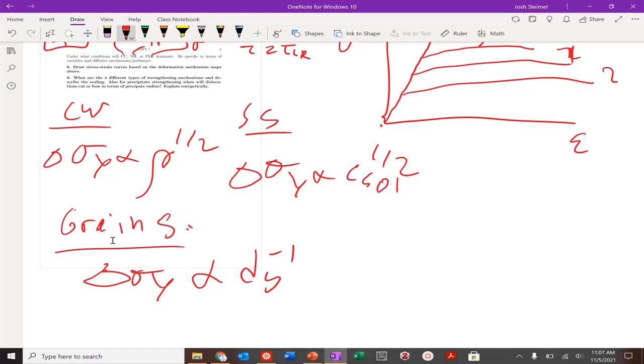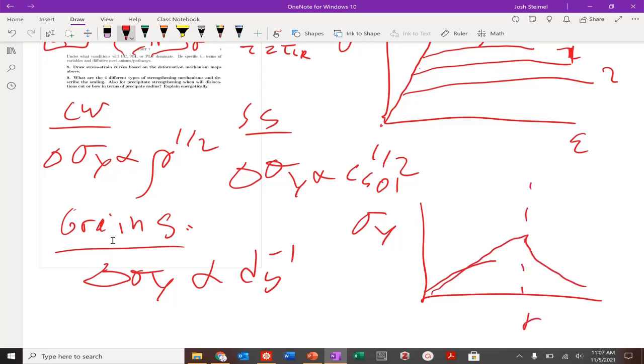And then we have our precipitate strengthening mechanism. We don't have an essential scaling there. But if we look at it here, we'll have a curve that looks like this. Actually, it looks like this and like this. So this is the critical radius. If I have precipitates, I want to cut small radii and bow around large radii. Because cutting creates surface area, and bowing is related to our curvature, and then that's it.